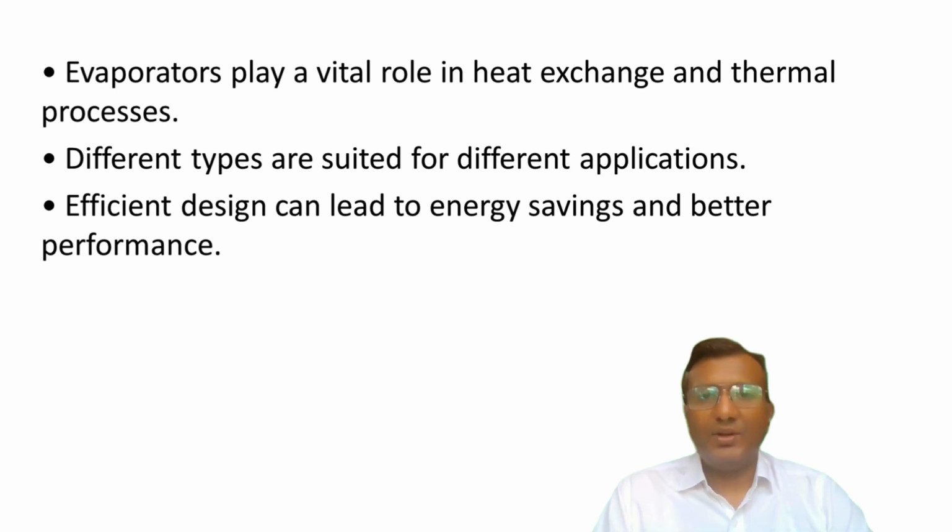To summarize, evaporators are vital devices that convert liquids to vapor, enabling efficient heat exchange and thermal processes across industries. Their working principle involves heating a liquid to its boiling point, with designs like natural circulation, forced circulation, falling film, and multiple effect evaporators tailored to specific needs. Applications range from refrigeration and air conditioning to food concentration, desalination, and chemical processing, showcasing their versatility.